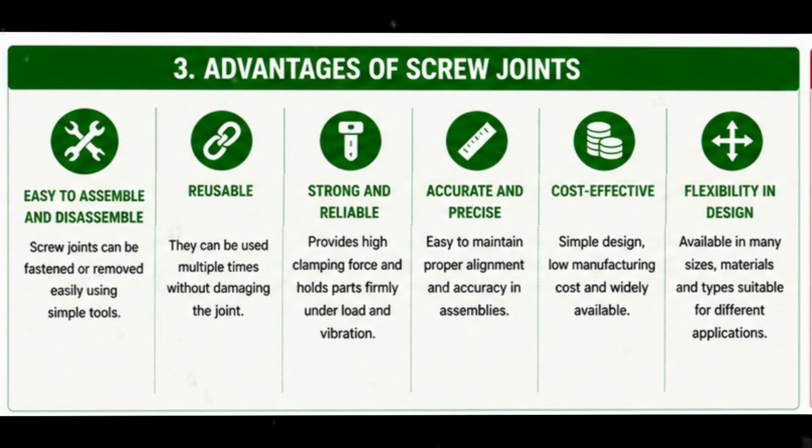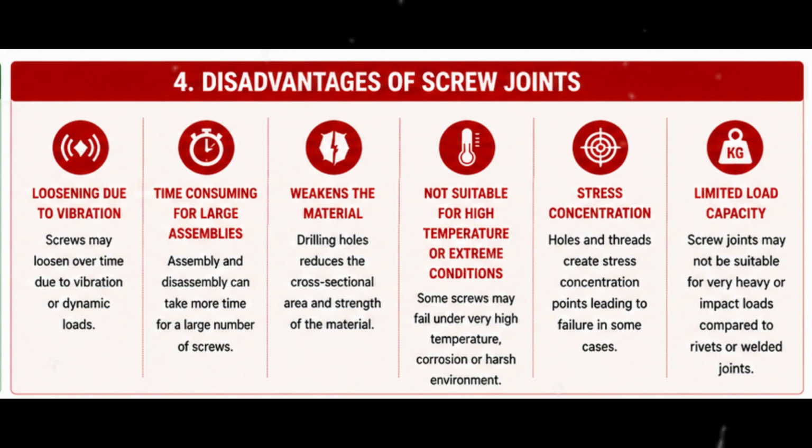But now comes the critical part. Their limitations: screws can be loosened due to vibration. This is very common in engines and rotating systems. Threads create stress concentration, which becomes the starting point of fatigue cracks. Drilling holes reduces component strength. In high temperature or corrosive environments, failure can accelerate rapidly. So, we cannot blindly use screws. We must design with understanding.